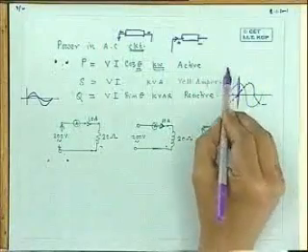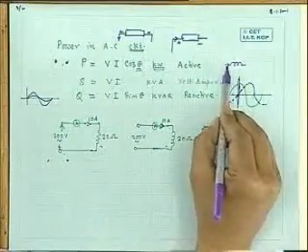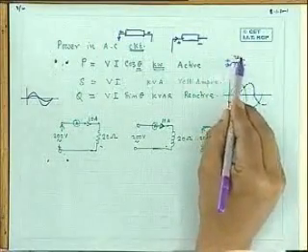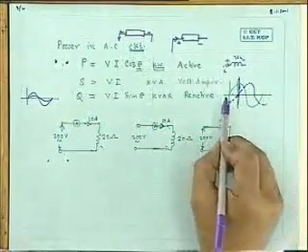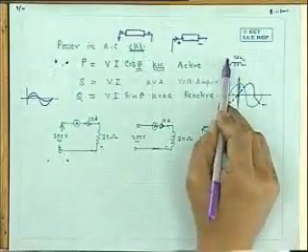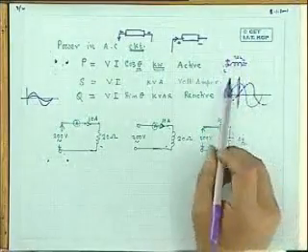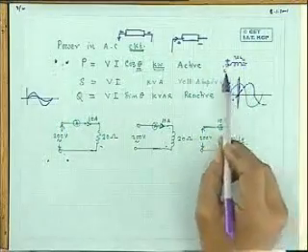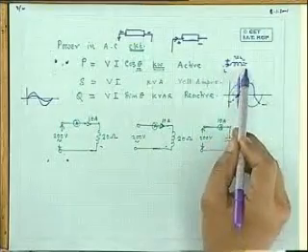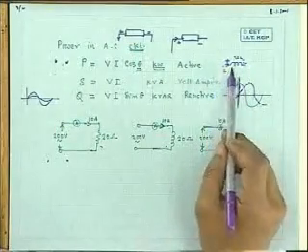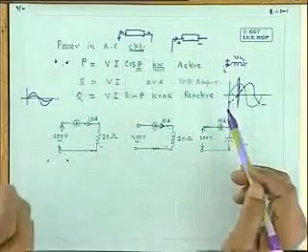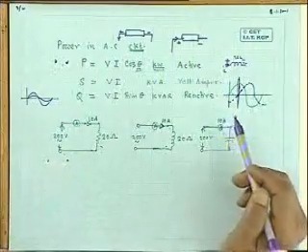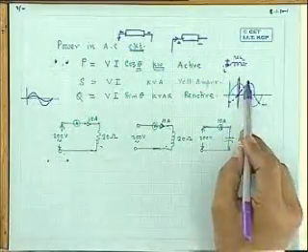But in case of an inductor, it is not like that. For example, consider this zone. Inductor is like this. This is the voltage I have plotted, VL, and this is the current direction I have assumed, from which I have got this solution. Now, between 0 to pi by 2, you find voltage is really positive. So, this is plus, this is minus. But what happens to current? Current I have shown here, but it is negative. Actually, current is flowing like this. Therefore, from the inductor, from the positive terminal, current is coming out. So, it acts as a battery sort of thing. It gives out power.